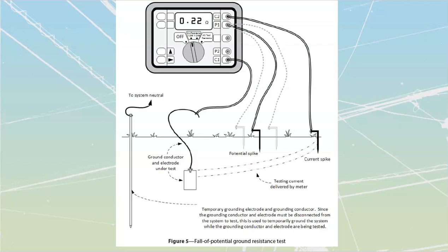Over the age of an installation, resistance to the ground is actually going to increase because we are going to form what we refer to as rust or oxidization. That is going to happen. It could be on the copper, it could be on the zinc that it's starting to eat away at the plate itself, and sometimes you actually have to replace your ground electrodes. Dry soil is going to change your ground resistance.